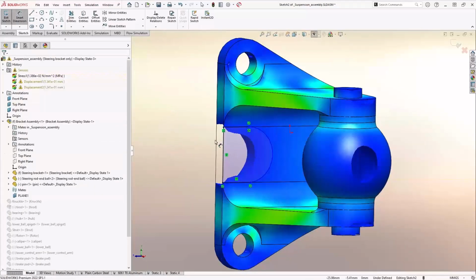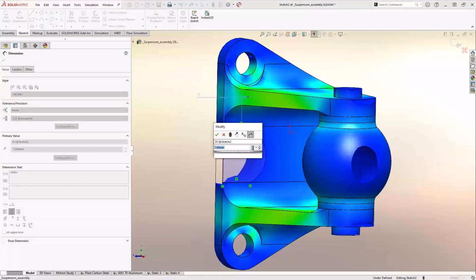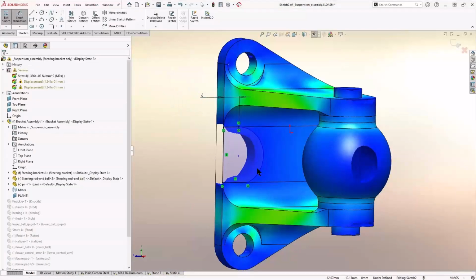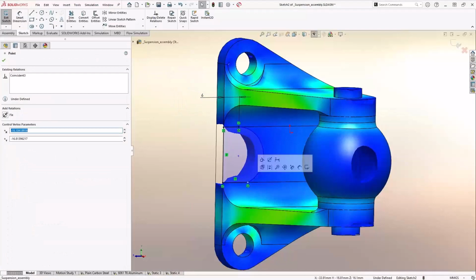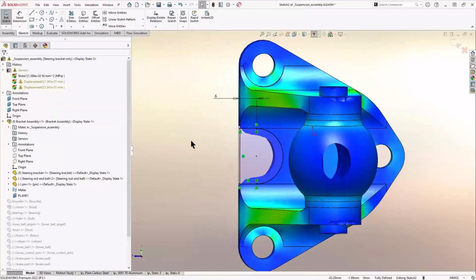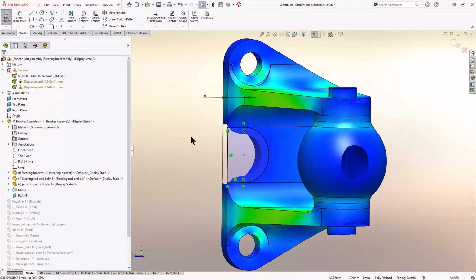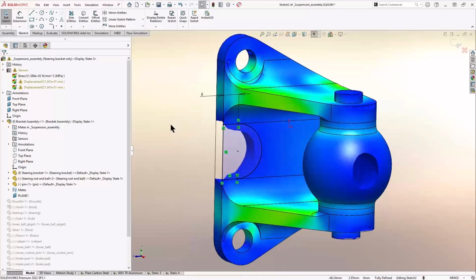Now, I'm a pretty big stickler for CAD modeling stuff inside of here, so I think I am going to actually throw a dimension on here. I don't know what number is going to work out real good, but I'm using this as if it was matching up the template underneath. And it looks like I could add a tangent relationship, and cool, I got a fully defined sketch. I hope you all do that when you're sketching. Fully define every time. If you don't know that saying, type it into YouTube right now. Check out fully define every time.